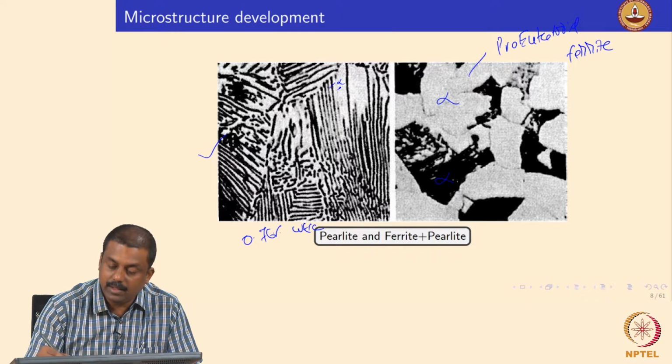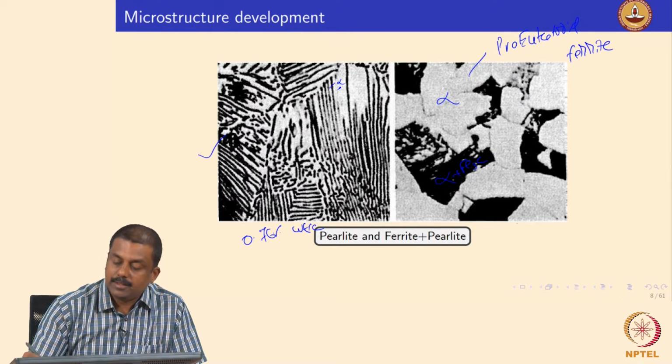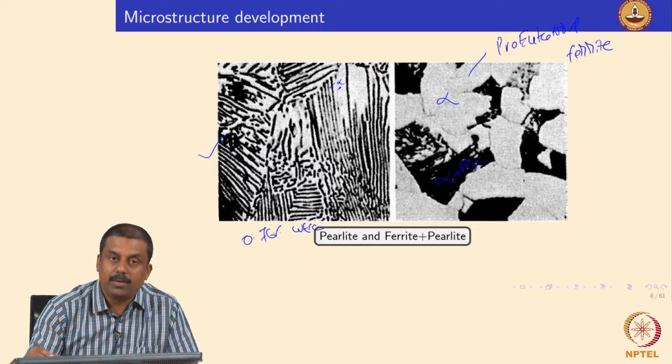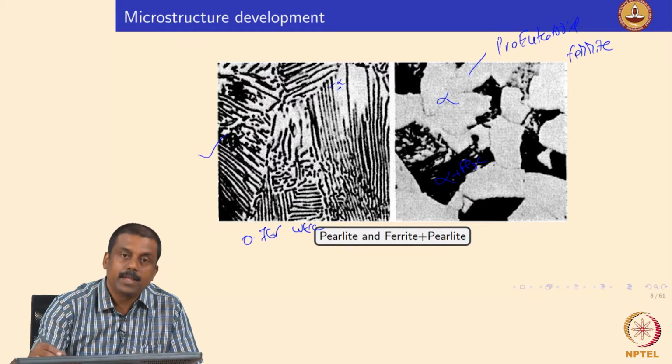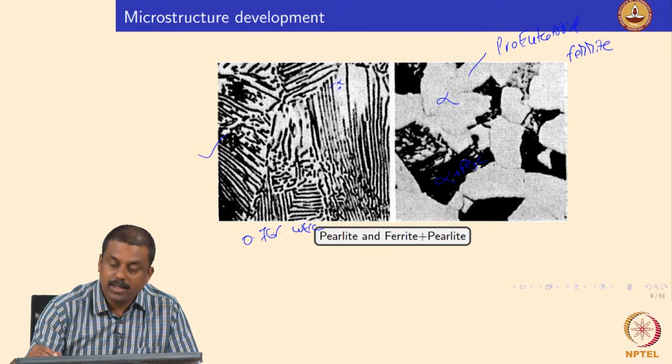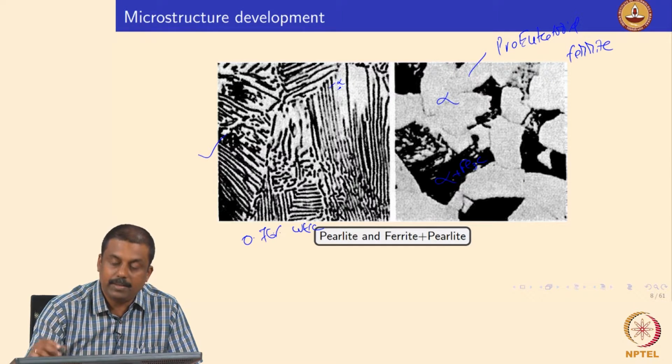So, this is eutectoid ferrite. Okay. So, a condition for this is your carbon concentration must be less than the eutectoid composition, which is 0.76, and most of our advanced steels' compositions would lie in this composition range, where if you are cooling sufficiently slow, you would end up forming ferrite plus pearlite, which is nothing but a mixture of ferrite and cementite.